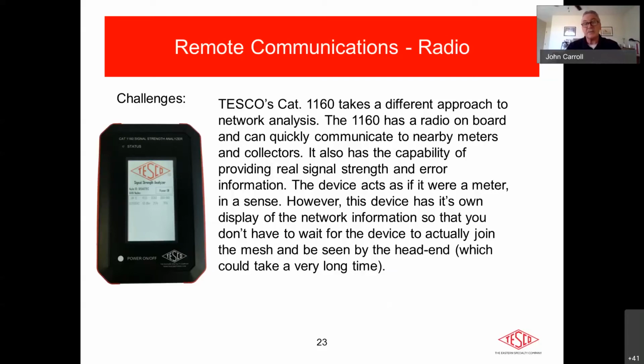They put in some low pass filtering to try and reduce that harmonic, and it reduced it enough so they could get a read from it remotely. So it's an unusual one, but it existed out there for sure. So these are things that we have to watch for with all of these hundreds of frequencies around everywhere. Okay, that was the application.